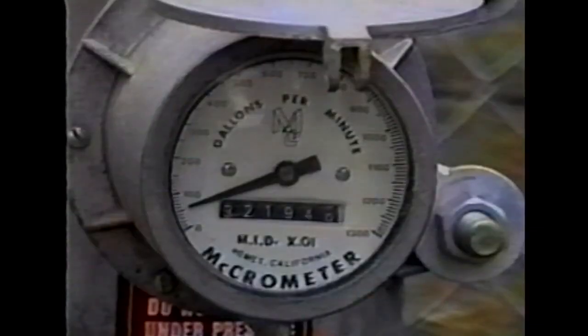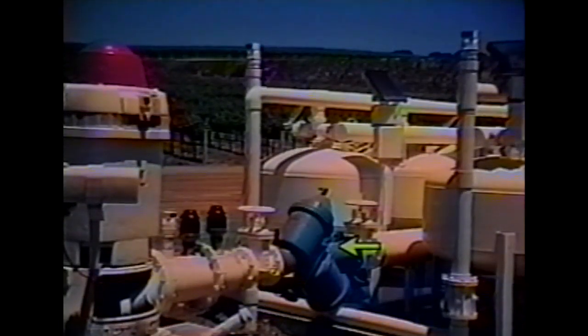Pressure gauges should be installed on both sides of the media tanks. As the media tanks get dirty, the pressure differential across the tanks builds up. Flow meters should be installed downstream of the media tanks, but upstream of any acid injection point. A pressure regulator is needed upstream of the filters for those cases in which there are different water sources with varying pressures. It helps to keep the backflush rates constant.